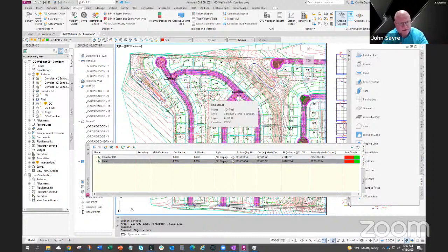So just so you know, Val and Charlie, there was a question about the workflow again, how we molded the corridor surface in with the overall grading. Like Charlie showed, you would initially grade the whole site if you were trying to balance, and then for more finite grading, you can go back in and add a corridor and all those roads like he just showed, and you can tell the corridor to follow that surface that you brought back from the optimizer.